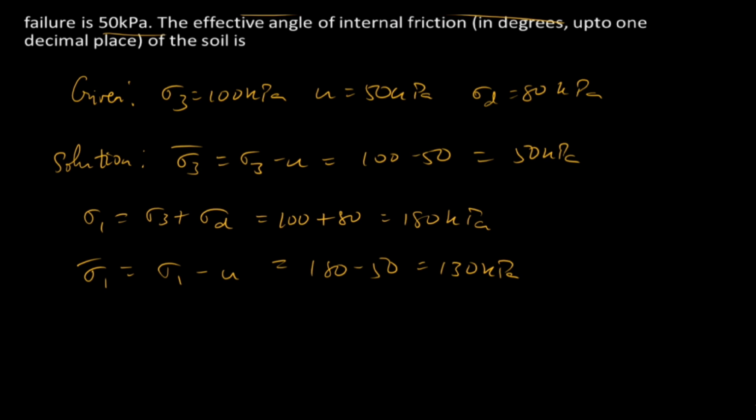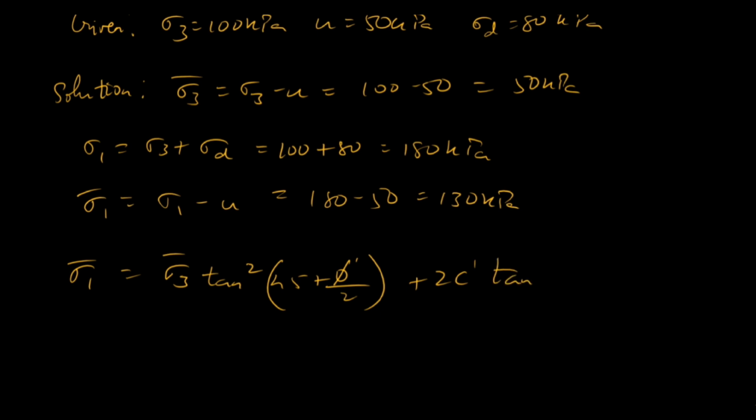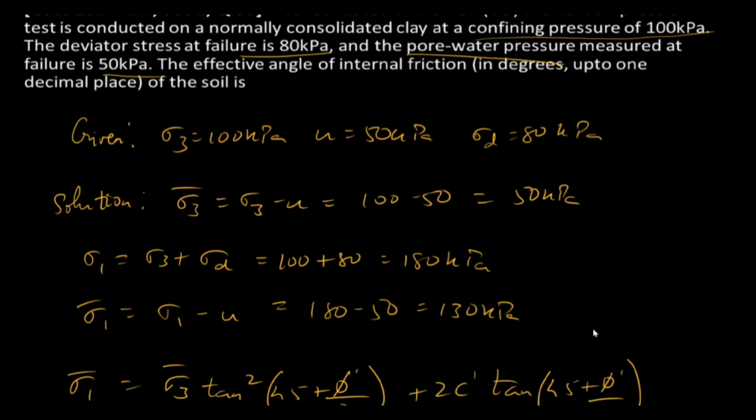So the stress relationship for effective stress will be sigma 1' equal to sigma 3' tan square (45 plus φ'/2) plus 2c' tan (45 plus φ'/2).